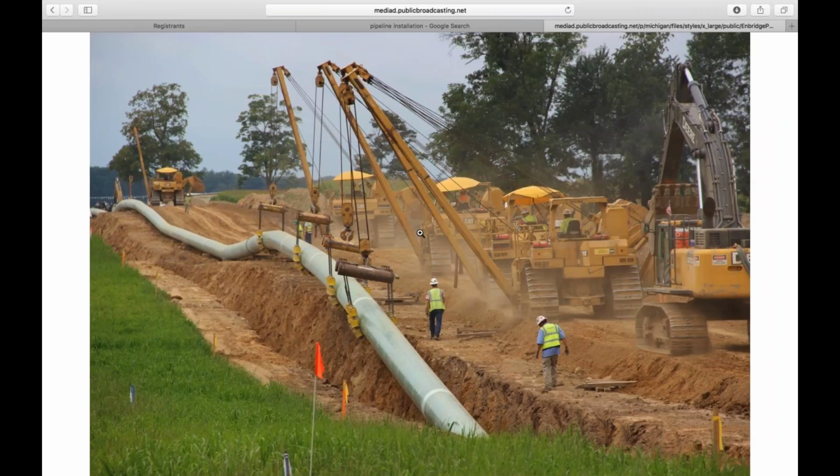That job order is going to tell us how we're going to pick a pipe, right? How we're going to pick up that pipe, where and what locations we're going to pick it up, how many different pieces of heavy equipment we're going to use to make our lift. All the way down to how we're going to weld it, how we're going to coat it, how we're going to test it. Okay, a holiday tester, right, for coating. So it's going to incorporate all that different material so that we can maintain quality control of the installation of this pipeline.